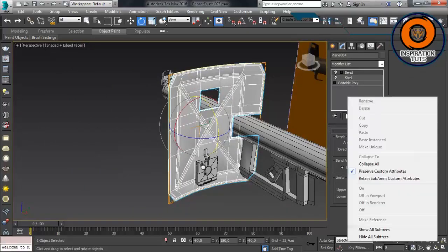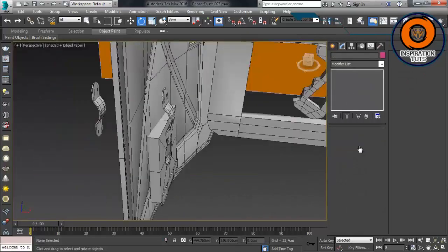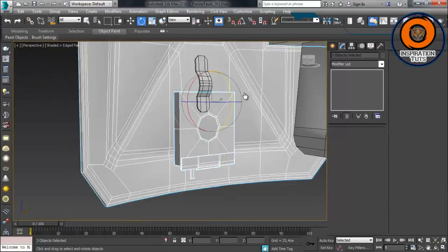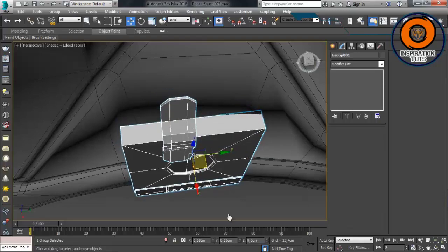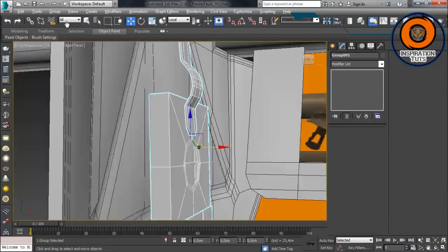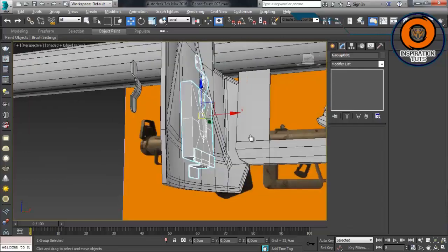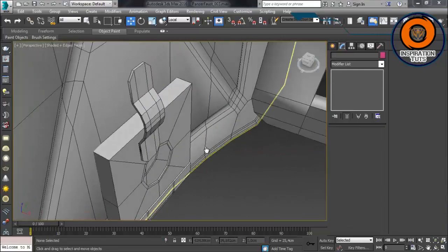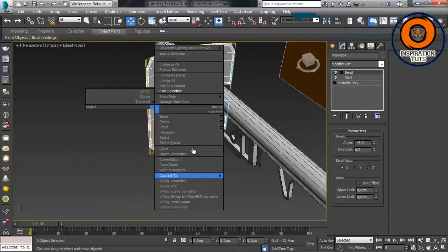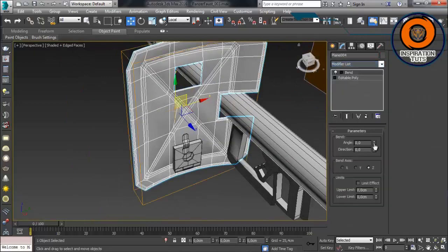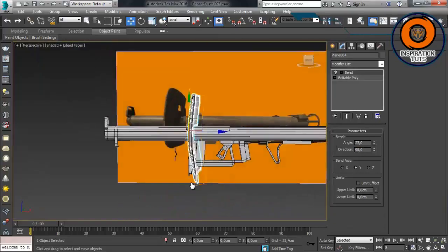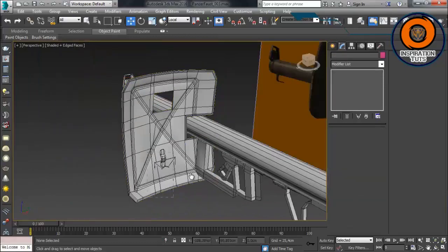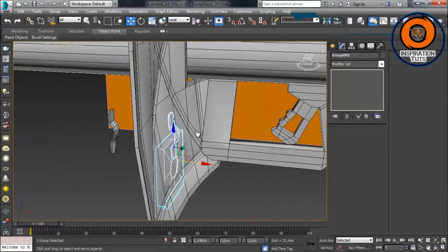and you've got to be careful with the bend modifier. I always used to struggle with it as a beginner because I didn't know that you need to select direction sometimes, even though you choose the angle and you choose the axis, for example, whether you choose X, Y, or Z, the object is not gonna be bent for some reason. First of all, because we didn't select the direction, because sometimes you need to select direction and the direction is better be 90 degrees or 270 degrees or something like that, just a kind of corner angle.